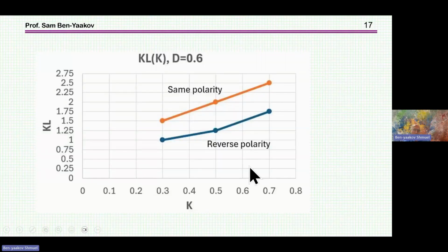So if I compare the two, I see that for different coupling coefficients, I was demonstrating it for 0.5, I get different values of inductance that I need in the coupled inductor. Now again, it has to do with what my target optimum is and what I'm looking for, if it is the ripple at the input of the inductor. And again, this is part of the information that is needed, because this doesn't say immediately how large the element will be and how exactly I'm going to design it.